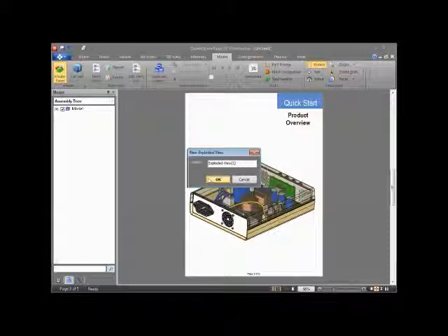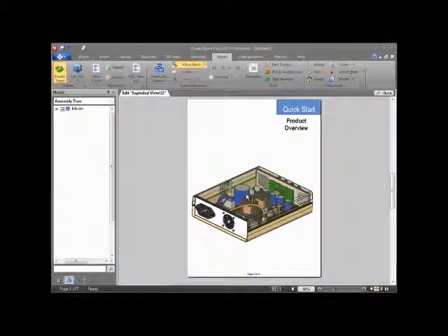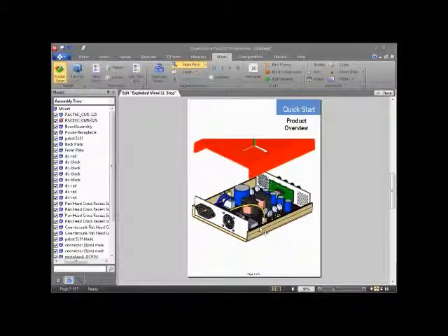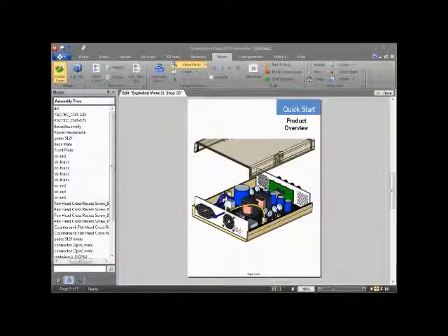And on the new exploded view, we're going to say OK. I'm going to click the cover, and I'm going to use the axis handle to pull that off. There's a number of different ways to create exploded views. You can type in numbers directly. You can just drag things out without thinking about them really. Or, like we just did there, which is most common, you use the axis to pull on the handle. So we're just going to go through step by step here and create a quick exploded view. Now, we're going to use this exploded view in a couple of